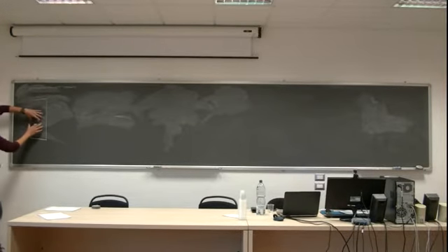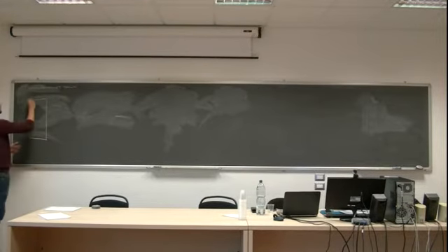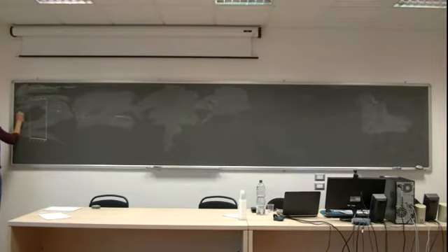As the wall is very long in this direction, I can assume that there is no heat transfer in the vertical direction. Usually in buildings there is no heat transfer in this way, but the main gradients are from the outside to the inside environment. As it is out, this is in, okay? And here we can have solar radiation, we can have a profile of temperature, whatever. And I want to know the response of the building because of that impulse.